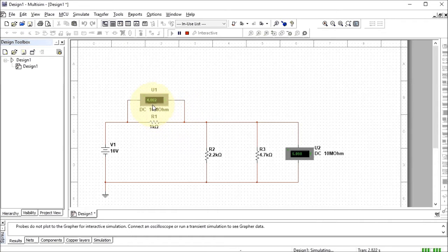So you can see we have 4 volts dropped across R1 and about 6 volts at point C, or the voltage dropped across R2 and R3. Notice that the 2 add up to the 10 volts supplied. Don't forget to record these values in table S.1.